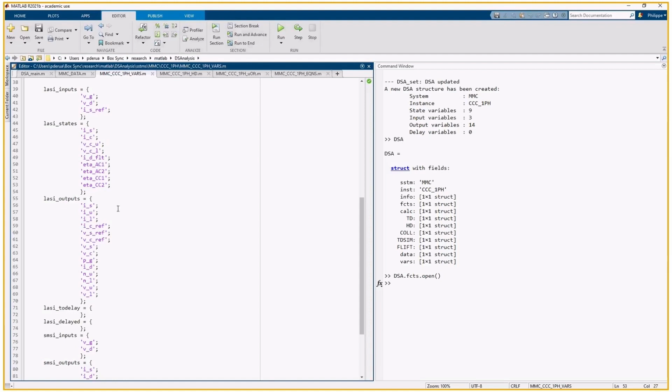I have defined on top of this a number of outputs. Some of these outputs are states, for instance, the alternating current, but I have also access to the upper arm current, lower arm current, the references for the circulating current, as well as differential mode and common mode voltages references. Plus, below you'll see a number of additional variables.